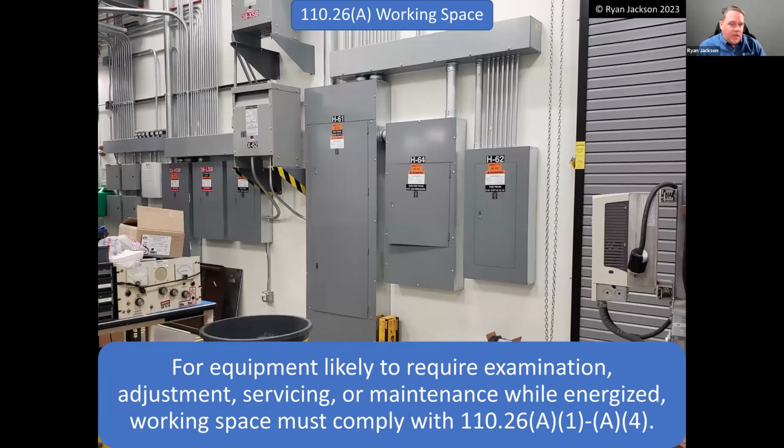That is examination while energized. Most people are going to say that panel boards like these will be examined while energized, at least at some point, right? Even if that's just measuring voltage. We have to troubleshoot things sometimes. So these have to comply with 110.26 A1 through A4.